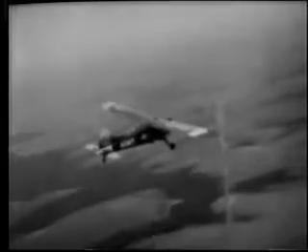We'll now return to the field. This time we will intercept the outbound track of 125 degrees. Again, parallel. We check the angle off. In this case, 20 degrees. Then double the angle to intercept. Here we will intercept our track at a 40-degree angle.